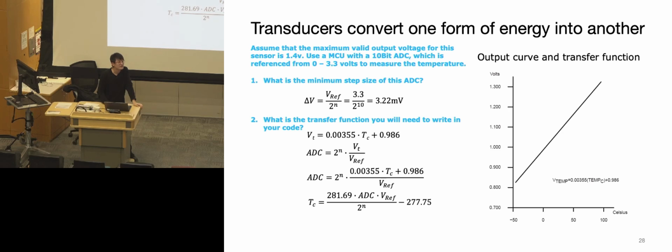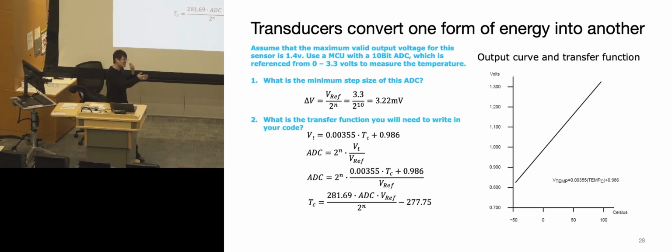Why would it be 2 to the 10 minus 1? Because we don't have a signed value we're calculating, so we would just use the full range, right? Yes, it's pretty much because we say we have 5 values on a scale, and then there's only 4 steps between them. But like PWM, 1 more, 1 less usually doesn't matter that much in practice, but it's good to have it right. Does anyone have any question on question 2? Okay, good. So for the next part,